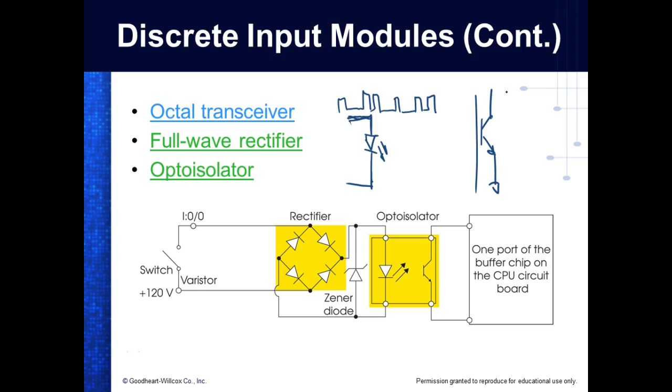Well, what they've done in the PLC is, if we looked at the PLC, we'd see this little thing right here, with these little pins. We see it as an integrated circuit, but that's your optical isolator, and it's built inside. If I do something I'm not supposed to, let's say I put 240 volts AC on that input, it's going to blow that thing up.